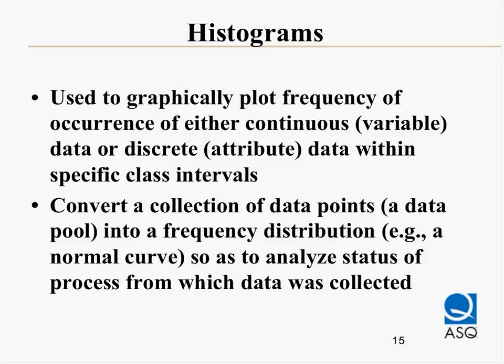Histogram. These are used to plot frequency of occurrence of either continuous data or attribute data, but within specific class intervals. What we want to do is fit the data points, known as a data pool, into a distribution, for example, a normal distribution curve, so as to judge the status of the process from which the data was collected.